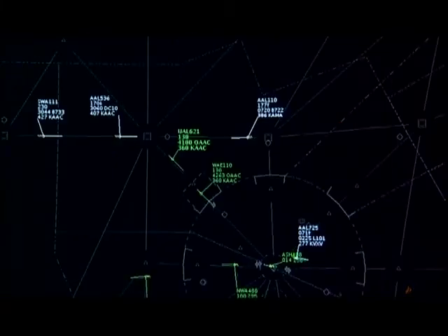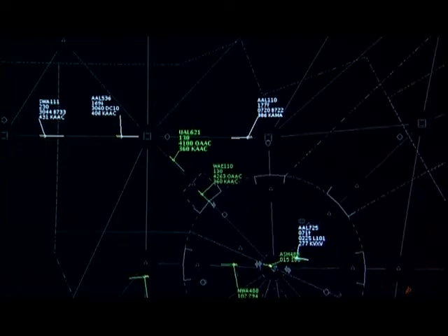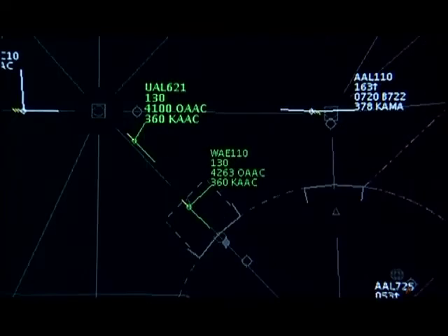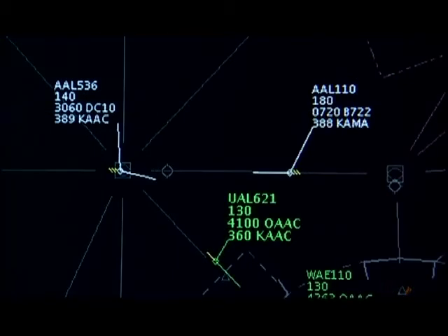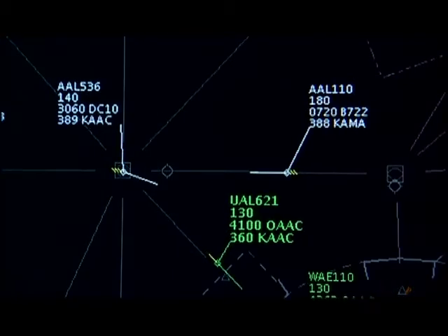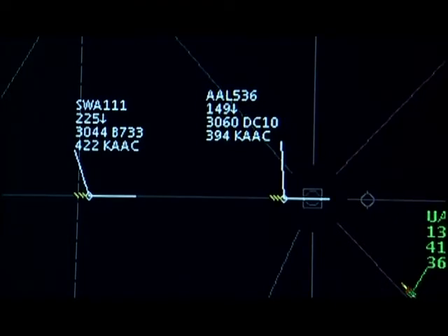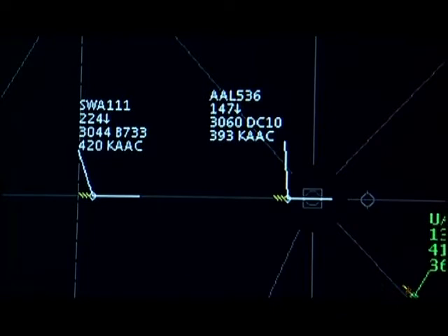Also, the farther out from Academy Airport that you start slowing traffic, the greater the impact it has on Aero Center. They may be forced to slow down all their traffic so it doesn't get bunched up at the arrival gates. Or they may not slow their traffic and you will end up with a big mess in your sector as more arrivals come before your existing traffic gets to the airport. You can coordinate speeds with center, but again, slowing traffic down creates a ripple effect through all of yours and center's airspace, so use speed adjustments sparingly.